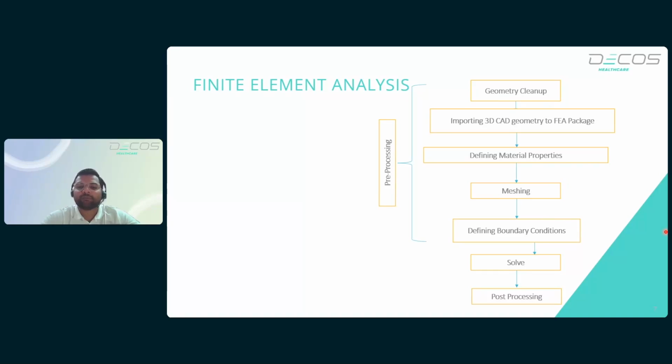Okay. Now, after the model is divided into a finite number of elements, we need to define real world conditions in the virtual world. These conditions are called boundary conditions. For example, defining the contact between two bodies, defining gravity, defining force, temperature, etc., of what exactly is there in the physical world, in the virtual world. So these are the boundary conditions, and whatever boundary conditions you put will decide what your outcome will be.